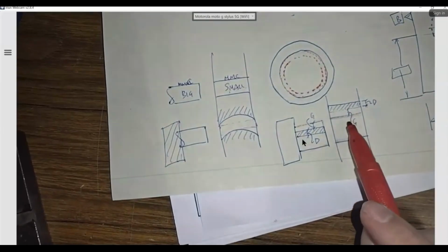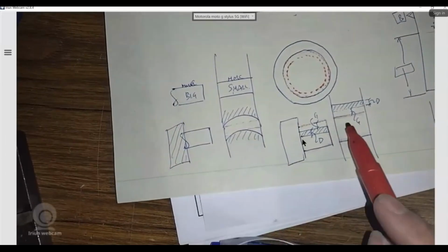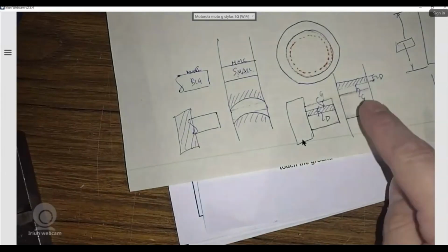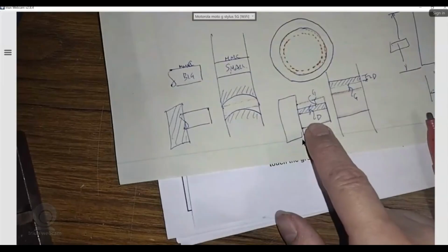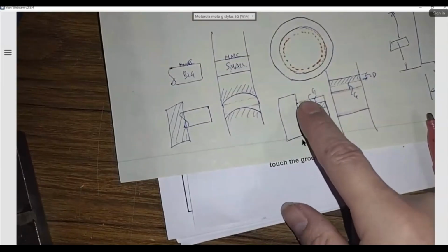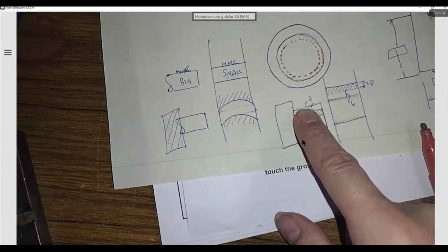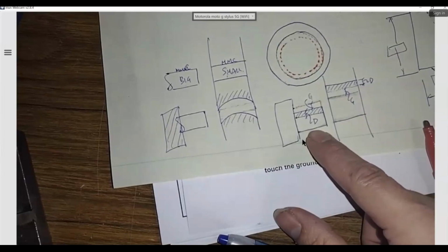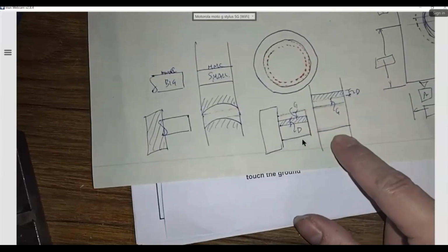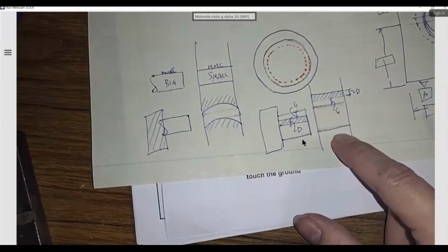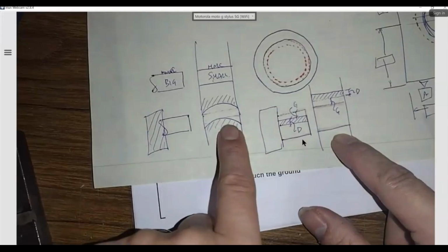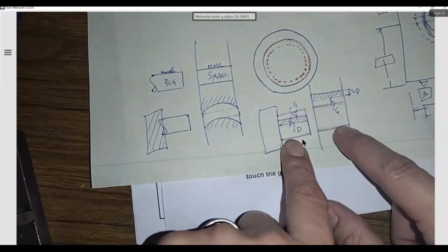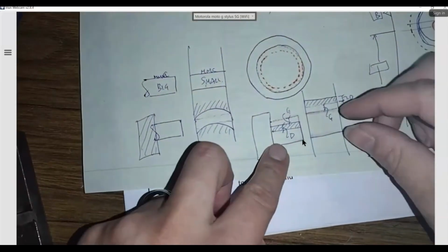And even when my hole can also vary in shape and become smaller, even at the worst case condition, which is the virtual condition, the hole still has to be bigger than my shaft, even when it's at the biggest condition and at the crookedest condition. Does that make sense? Virtual condition for a pin is the biggest I can get plus the crookedest I can get. And if the hole got smaller, the worst case condition for the hole is the smallest I can get, and then take away the crookedness because it makes it smaller. Does that make sense? Those virtual conditions, then, to make it safe, I'm going to make it even bigger.